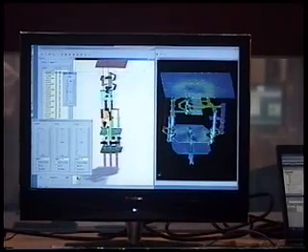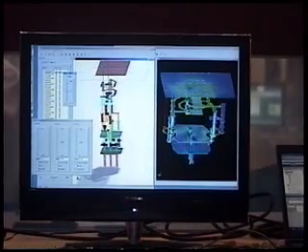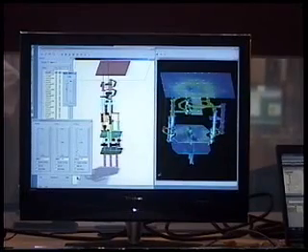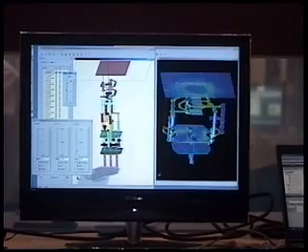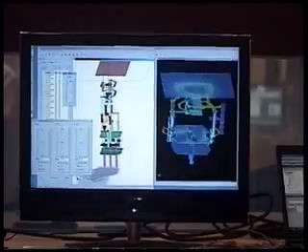the accuracy of where you place your vias, because especially for multi-layer structures, one wrongly placed via can destroy the structure and the design. So you want to verify that before you do your simulation.